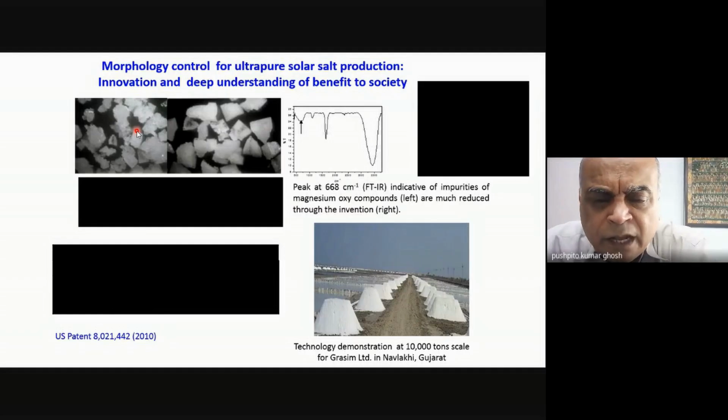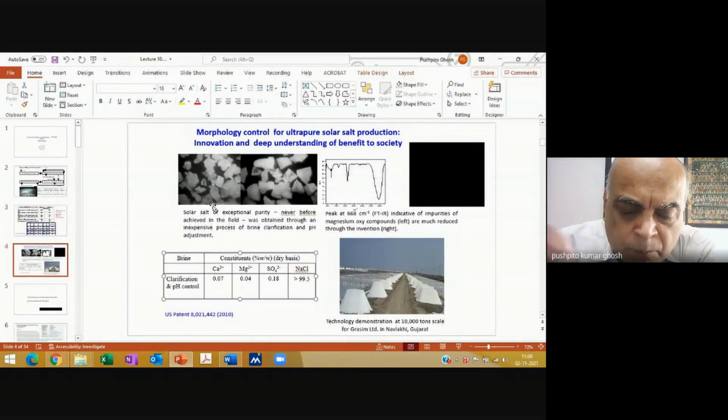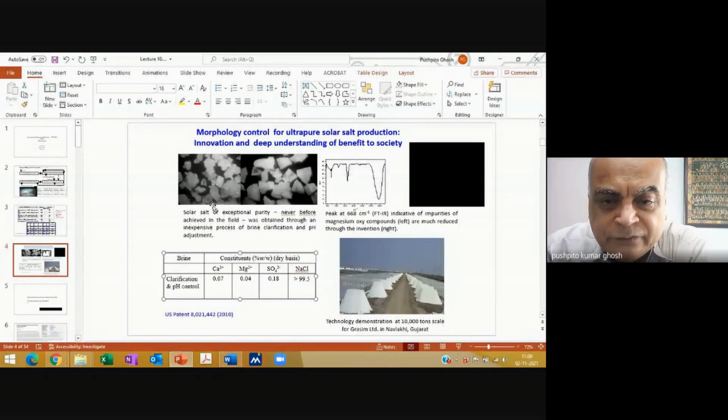How can you make a solution which is hazy, cloudy into clear? We can add alum. Wonderful. You can add alum. And believe it or not, that's exactly what we did, and which led to a breakthrough technology. You're so right. Just before putting it into the salt crystallizers, the brine was treated with alum.